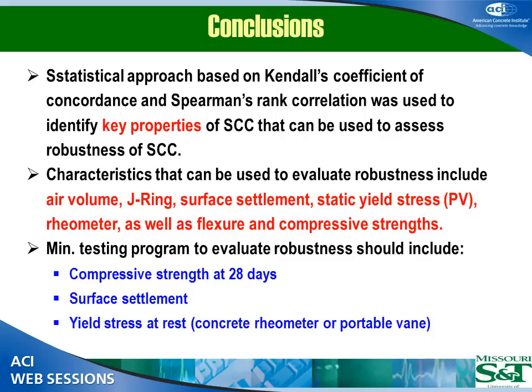But with the superplasticizer dosages, it seemed as if it was more sensitive. At 7 days, you're right. One of the graphs that was very steep was the 7-day compressive strength. At 7 days, if you are putting a lot of super, you're delaying setting and what have you. Yes. Thank you.